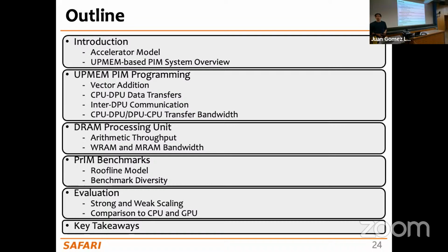What is the routing density? When you design a chip, you need some lines, right? Metal wires to connect different components. So the routing density is how many of these wires you can have given a certain amount of area. Higher density means more of these lines, and that means that you can also afford a more complex design. Okay?